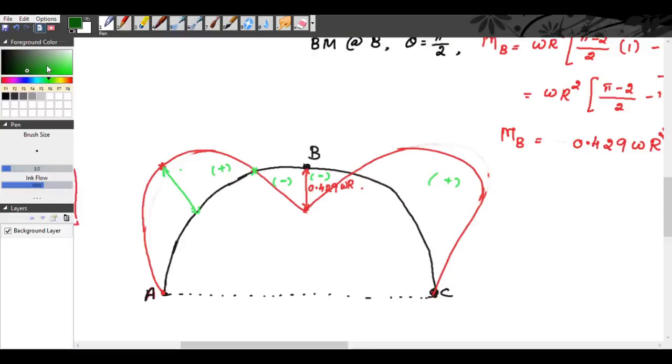So before that, for drawing the maximum bending moment, this is our point O. So we will join these lines to O. See, from maximum, you join this to O. From this point of contraflexure, you draw a line to O. From B, you draw a line to O. So similarly, from this side also.